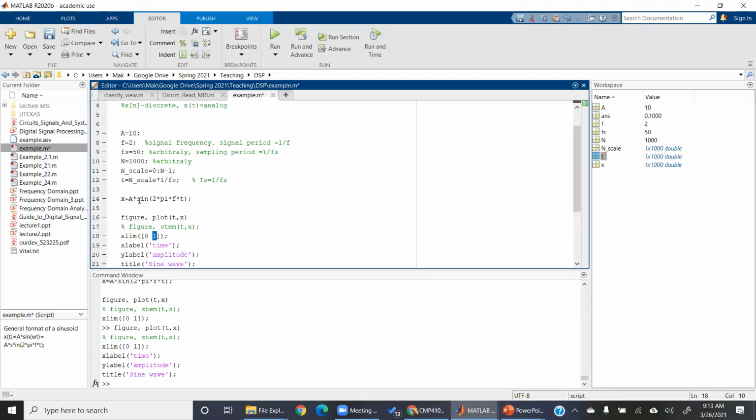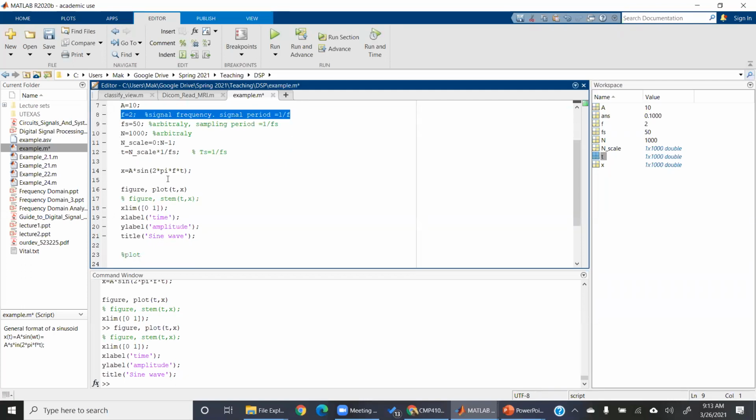And the answer lies in the period, the actual period of the signal, because here you already displayed the signal, you already reconstructed it, and you're looking at the actual time scale as to what would be the length of the time axis for a given number of cycles. On the other hand, when you're reconstructing the signal, you're looking at the sampling period. So that is why when we're defining the time scale, we looked at the sampling frequency and we used it to generate the time scale.